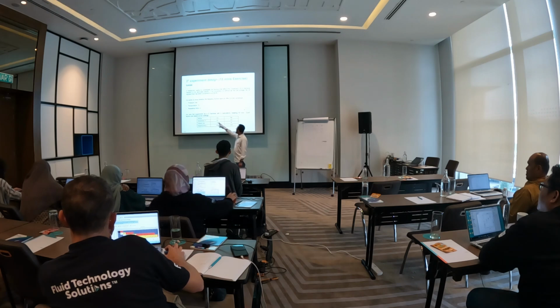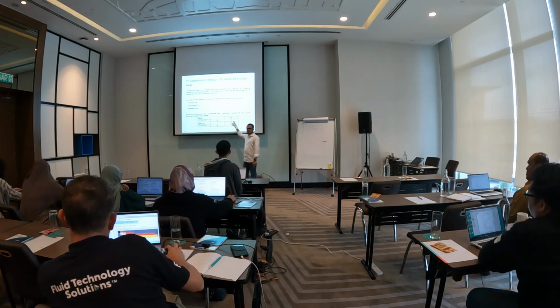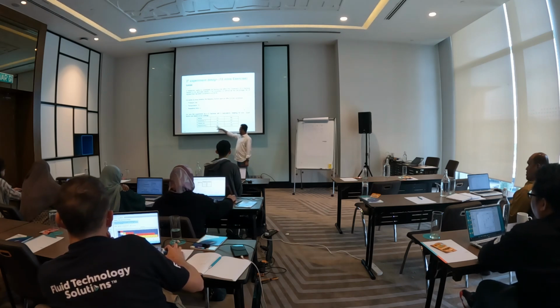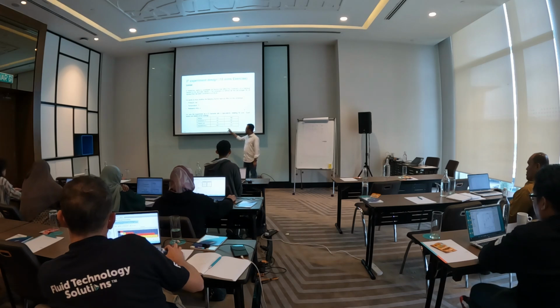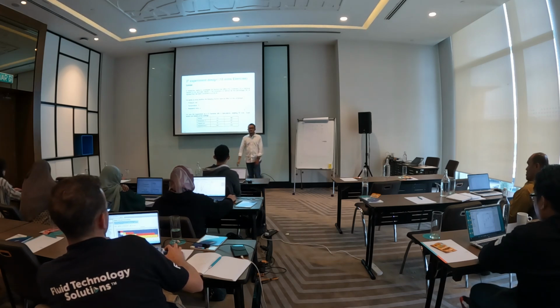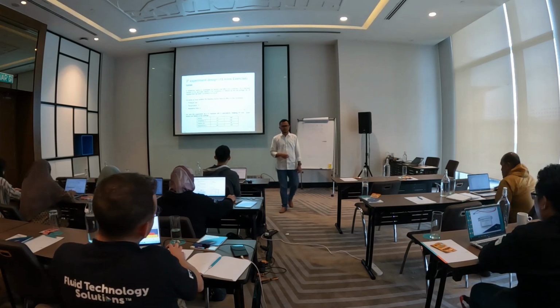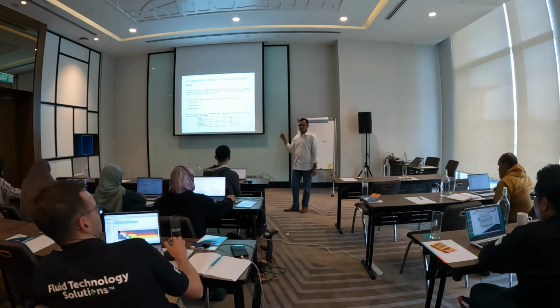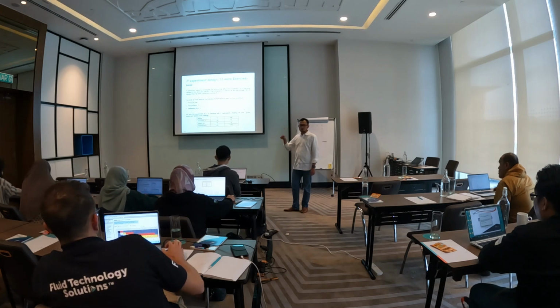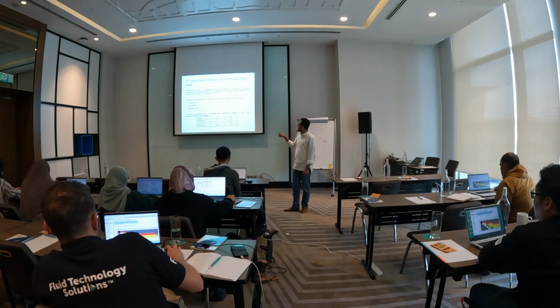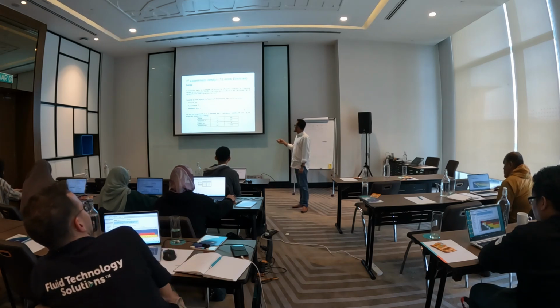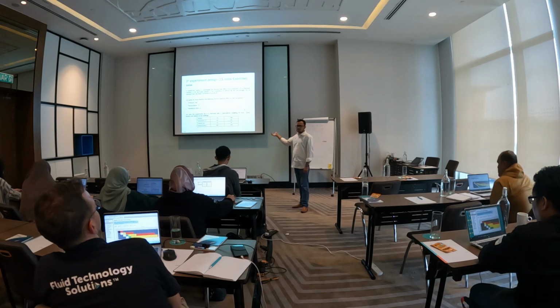Temperature is low 100 degrees to high 200 degrees, pressure 30 bar and 50 bar, and residence time 600 seconds and 1200 seconds. So you can open your Design Expert software and select this full factorial 2 to the power of 3, and then fill up the information on the factors and the low and high settings.